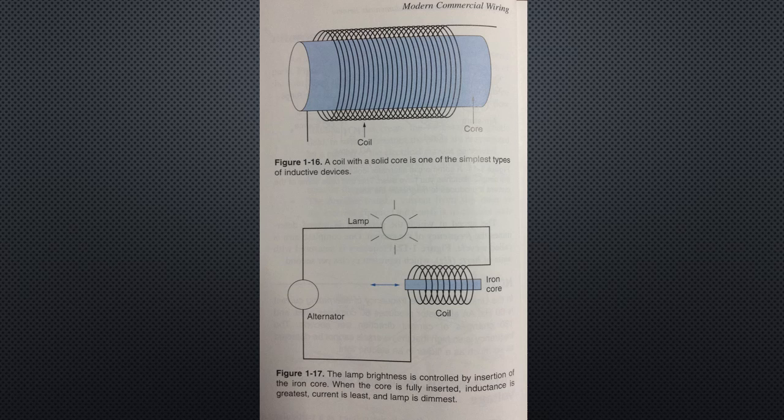The major difference between an AC circuit with resistance alone and one with inductance is response speed. The current flow in a circuit having only resistance will change instantly if the voltage changes. Current flow in an inductive circuit will respond slowly if a voltage change occurs. This opposition due to inductance is called inductive reactance. It is measured in ohms, as resistance is. The symbol for inductive reactance is XL, L for inductance, which is measured in units called henries, or capital H.